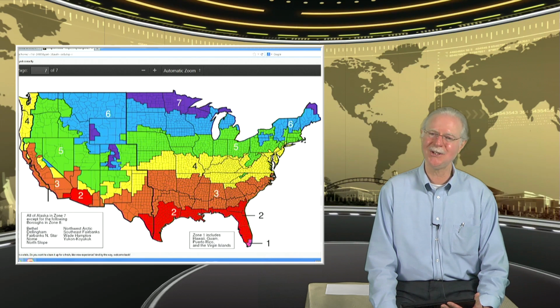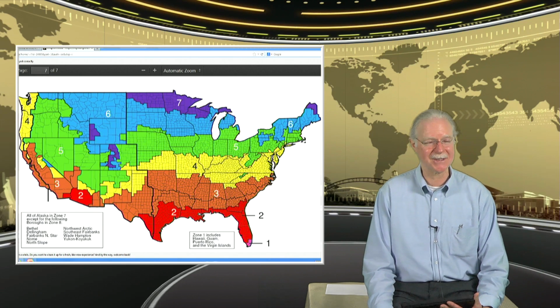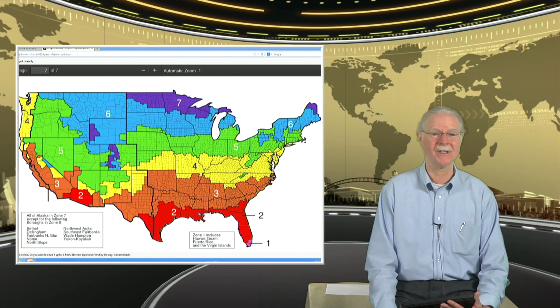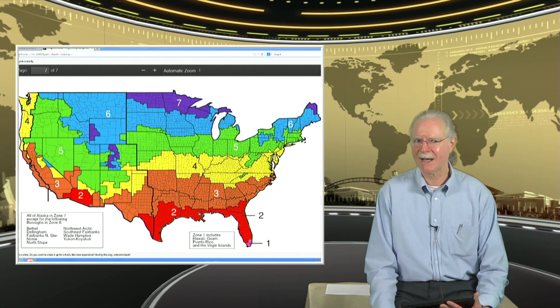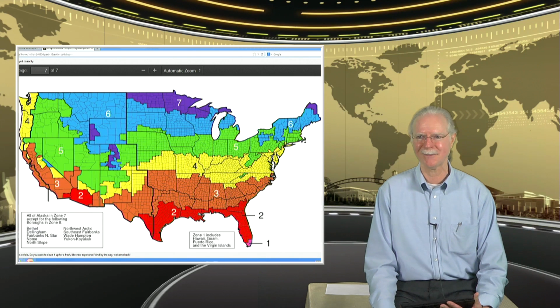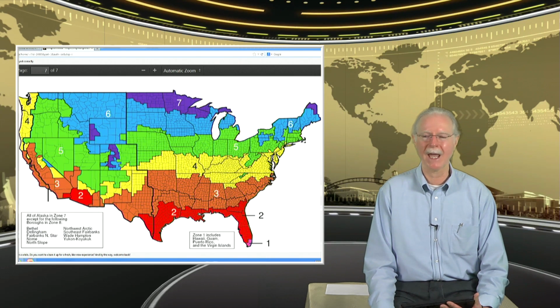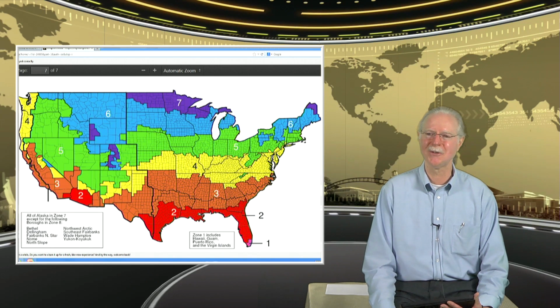So your strategies will probably be different there than if you were in Indiana, for instance, where you're not likely to see those temperature extremes in the summer. You're going to find consistent heat. Windows are a great example of something that you might do differently in those locations, because all of a sudden, capturing radiant energy during the day in a climate that doesn't have many clouds might be a really good strategy.